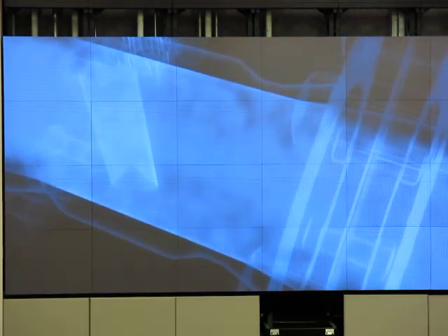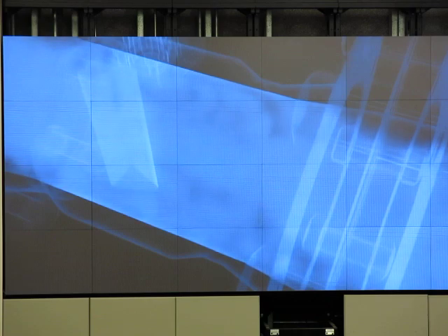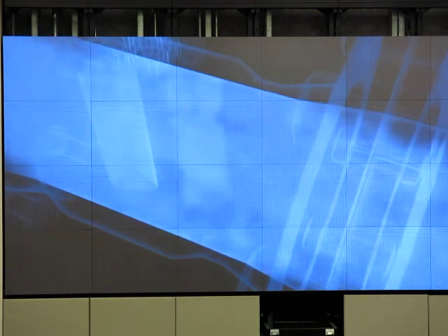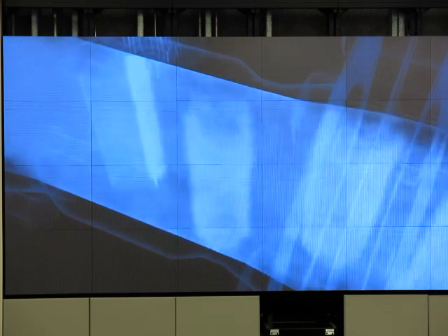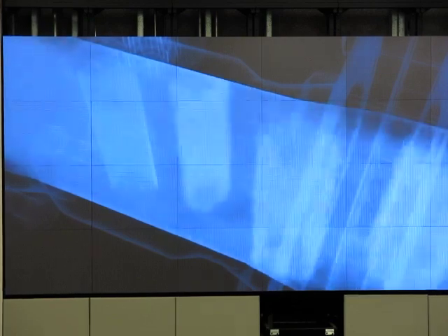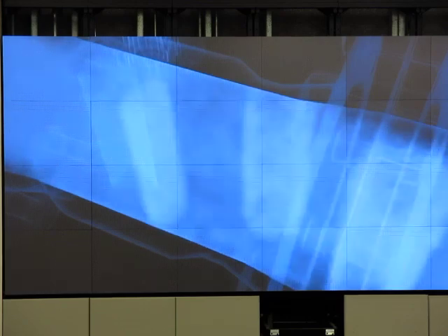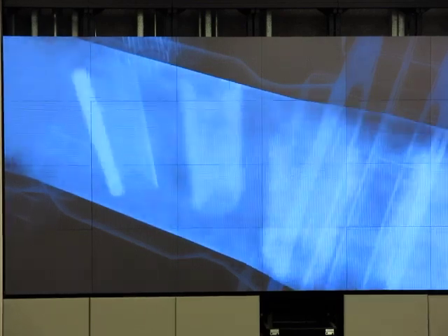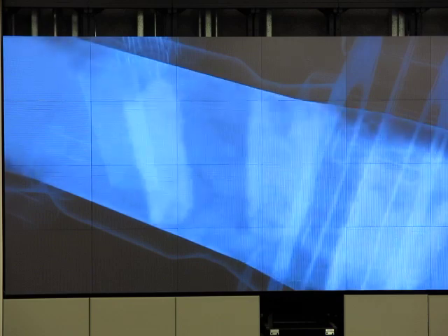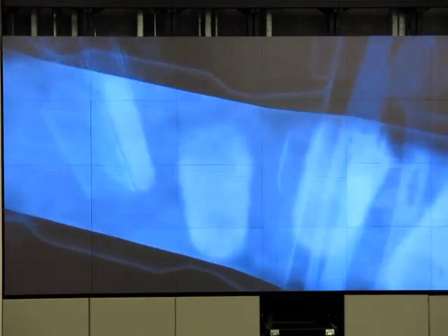If the fluid is not flowing, no vortices form. As soon as the fluid starts to move and reaches a certain flow rate, vortices gradually appear downstream of the bluff body. These vortices are detached alternately on either side of the bluff body and are carried away by the flowing fluid. Zones of high or low pressure now appear downstream and thus create a phenomenon that is known as the Karman vortex street.